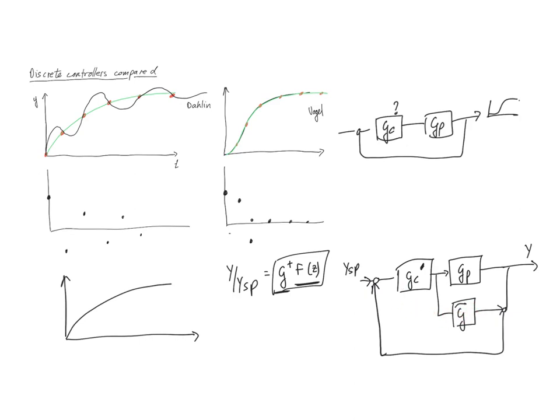In the cases where we are using this for discrete control, we will obviously have sampled and held the controller outputs. So we'll be working with a held version of the model, and in fact we will also be working with a sampled version of the measurement output.